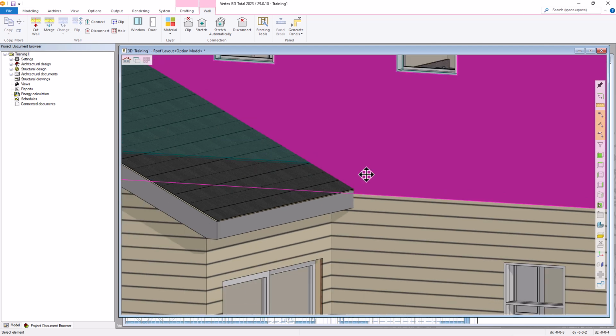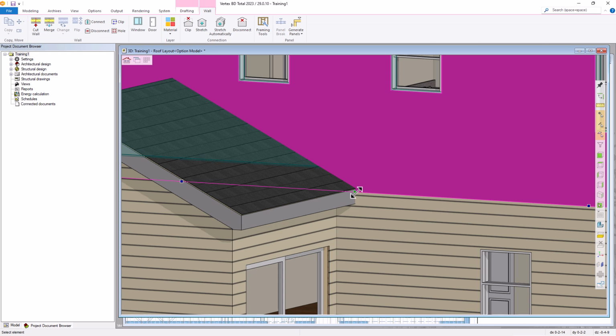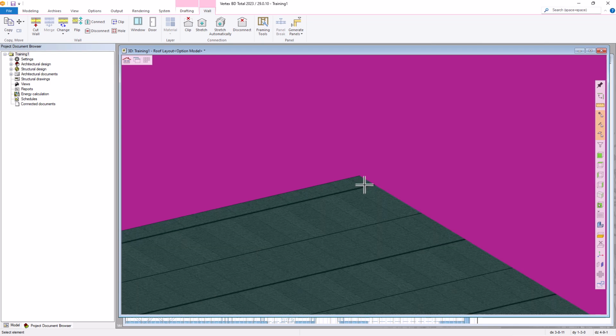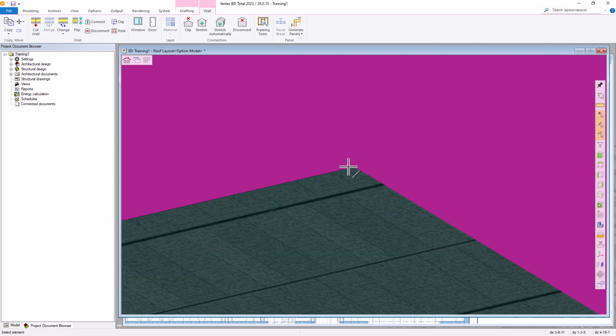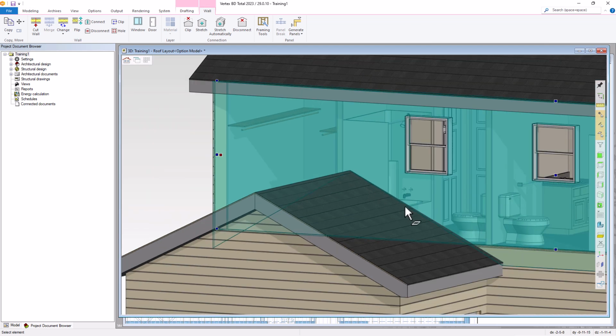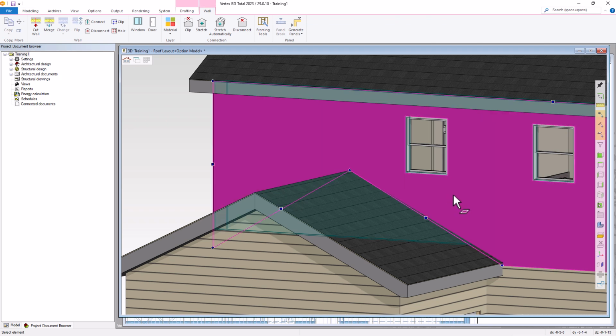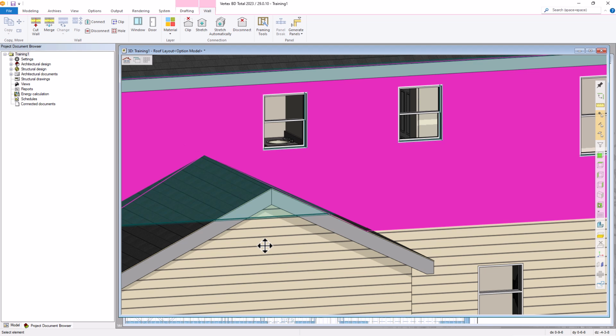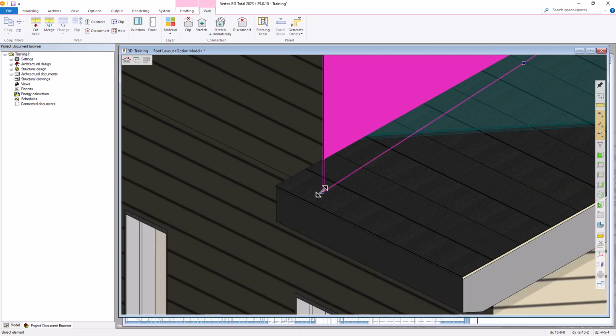And we'll select this again. Now you see that we have a point there. I'm going to go over to the middle grip point, which is the square shape. Right click. We're going to add another point. And I'll just drop one somewhere about there is fine. Go back, click, and we can take that point that we added and bring it up to this intersection. Select the wall one more time. Let's go to this side. Bring this corner up.